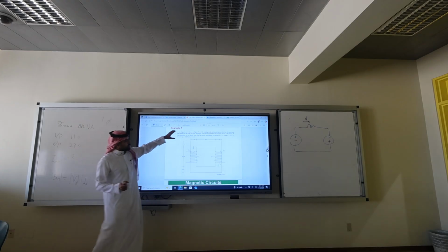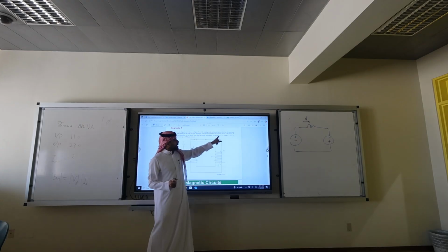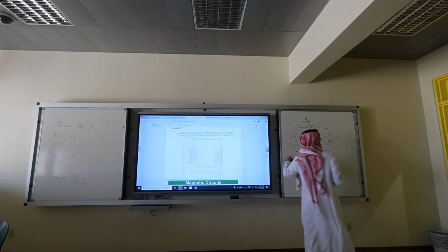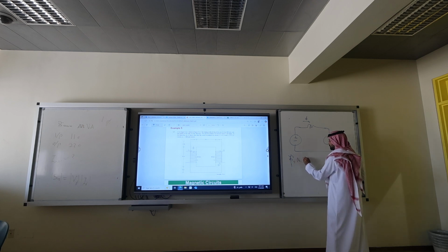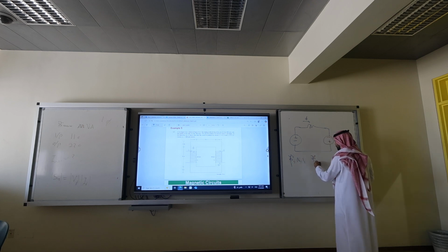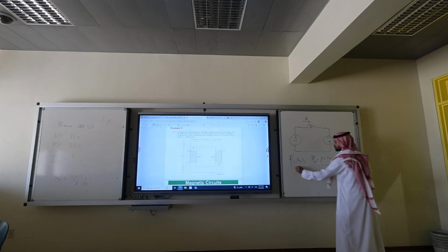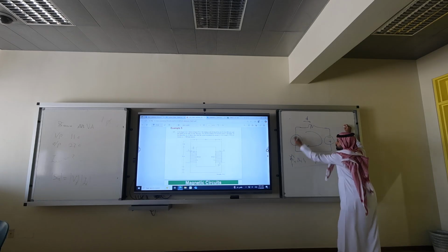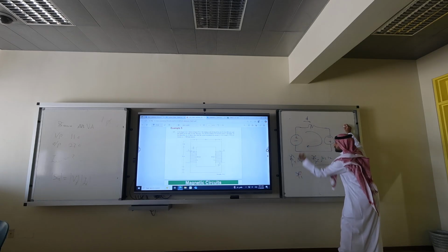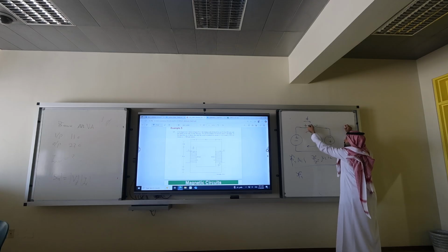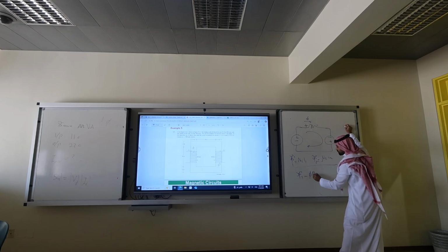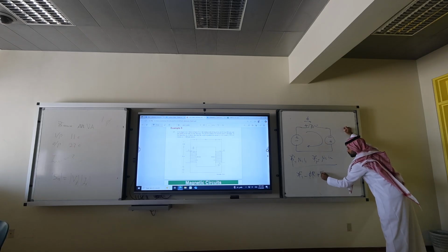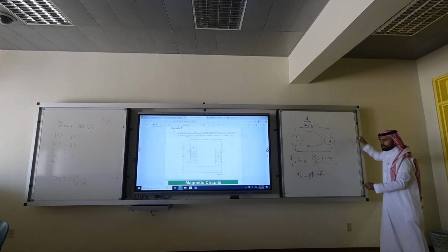It's easy. If you read the question, he's giving you the currents, I1, I2. So what is F1? N1 I1. What is F2? N2 I2. Do a KVL. Voltage rise or voltage drop? If you do the classical method, you will just reverse the direction.